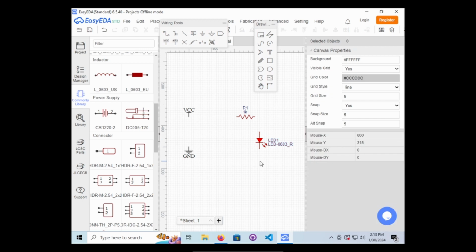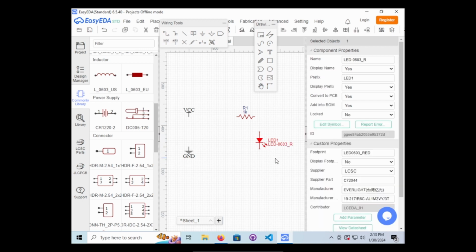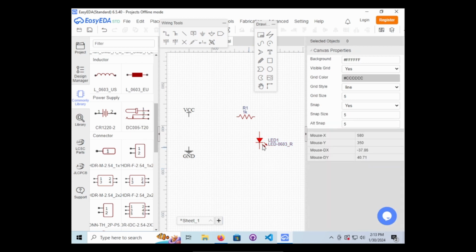It's kind of nice. Now we're going to talk about footprint size real quick. See, this one shows you the manufacturer it's linked to. You can change all this. These are just their default library pieces. You can change it to whatever parts you want, so that when you generate your BOM, your bill of materials later, you'll have the parts that you're going to order yourself, obviously.